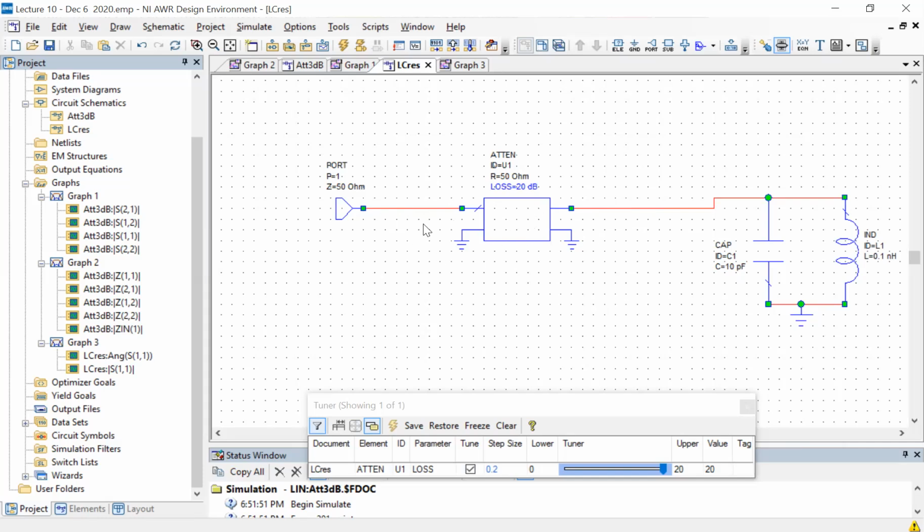Okay. So lossy sections in between are very bad. They cannot be calibrated out, because they will kill the signal. They cannot recover the signal to noise ratio, right? A calculation can only scale the number, but it will scale both the signal and the noise. So signal to noise ratio will not be recovered, and you cannot measure the magnitude reflection coefficients carefully if you have a big attenuation in the middle. So it's very important to keep this in mind and make sure that you don't have losses when you're looking at reflection coefficients like this.